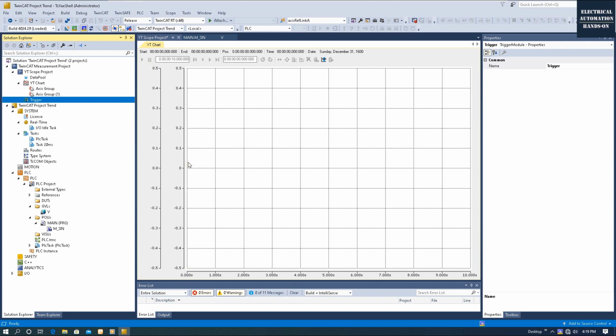This is very flexible. For example, if you are recording one motor output or one servo motor output, you have speed, current, torque, and precision. So you could have 4 different axes: current, speed, torque, and precision. But the time is the same, right? So you like to analyze at that short period when the current goes high, suppose the torque should go high, and which position that high torque happens. So you can diagnose if there's a gearbox or something wrong in that short period. So this is very convenient.